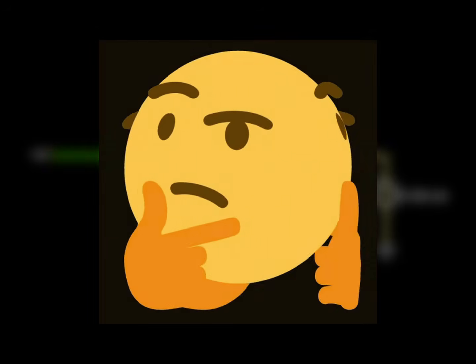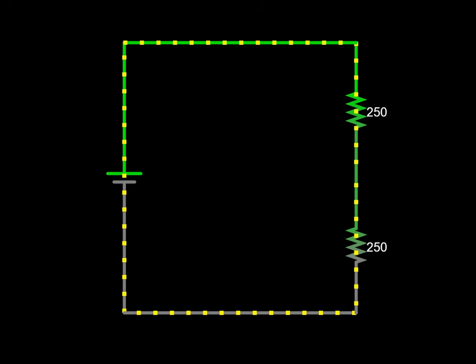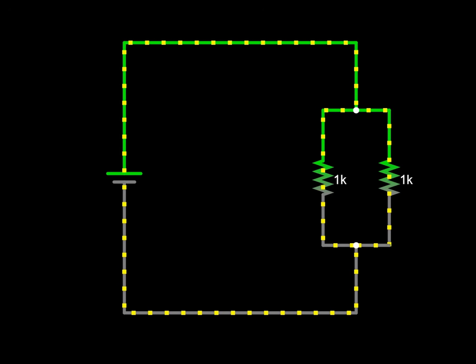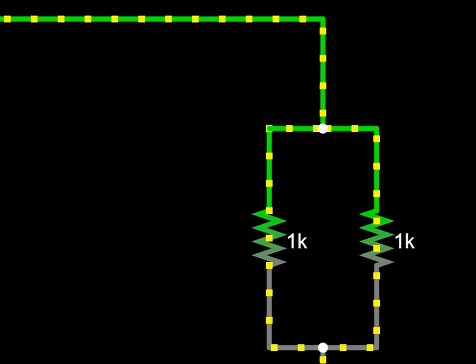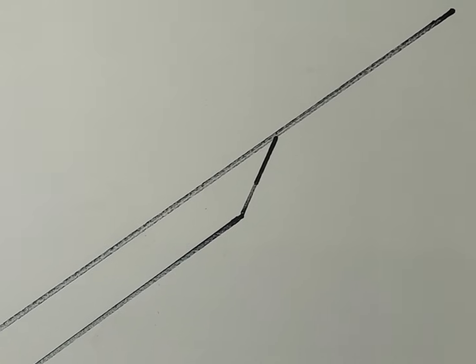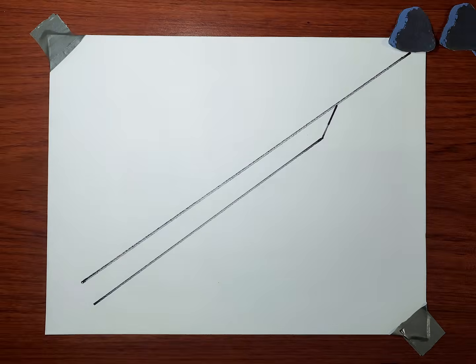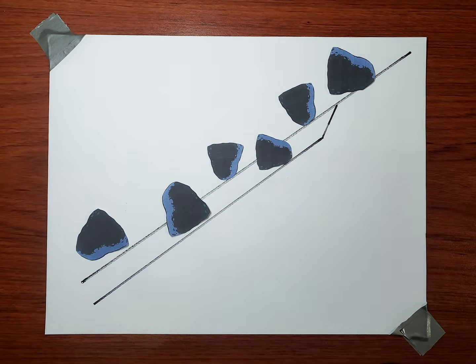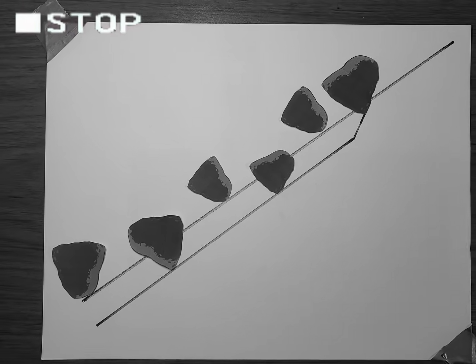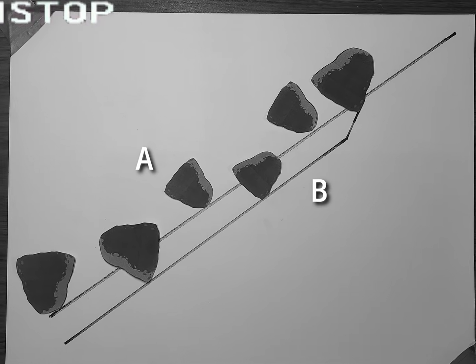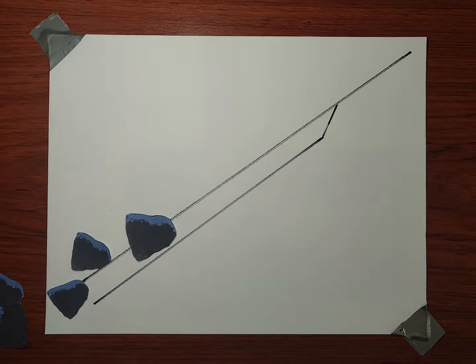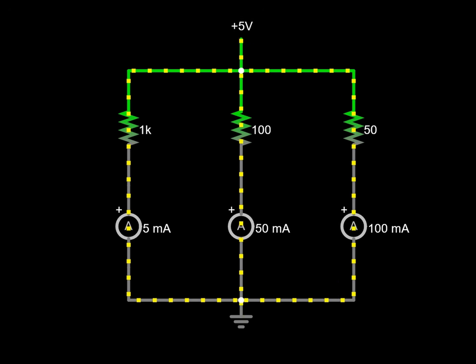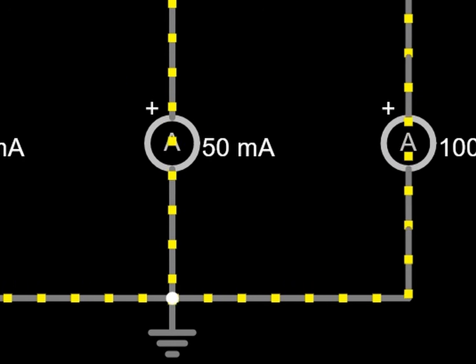Then, what is a parallel connection? Let's get back to our model and move things around. The two resistors are now in parallel. So, our supply now meets the two at the same time, right at this junction. It's as if the rocks had to face a decision and can now take a second route. Some of the rocks head down the usual way, but others take the new route. Now, we have a different number of rocks in path A and path B, but we have the same potential in either route. That's because, in parallel connections, voltage is preserved, while current gets split through each load.